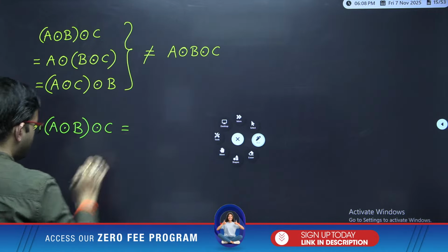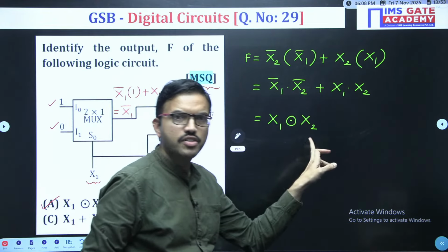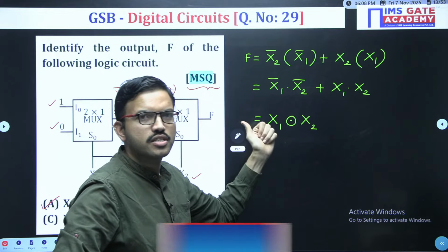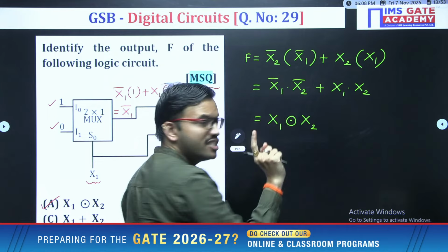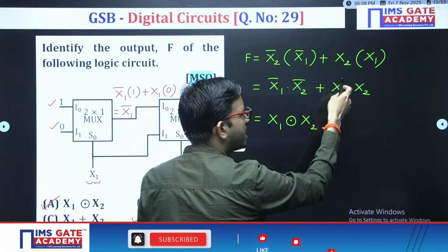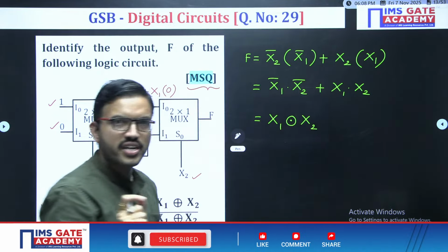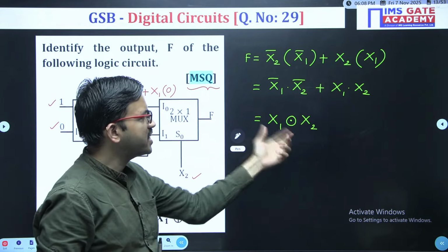See, very simple. Just like when you have two variables x1, x2, among which you want to perform XNOR, what is the expression? Both the variables complemented individually and then logical AND, then both the variables normal and then logical AND. After that, among those two terms you perform logical OR. That is the basic definition of the two-input XNOR gate, or two-input XNOR expression.